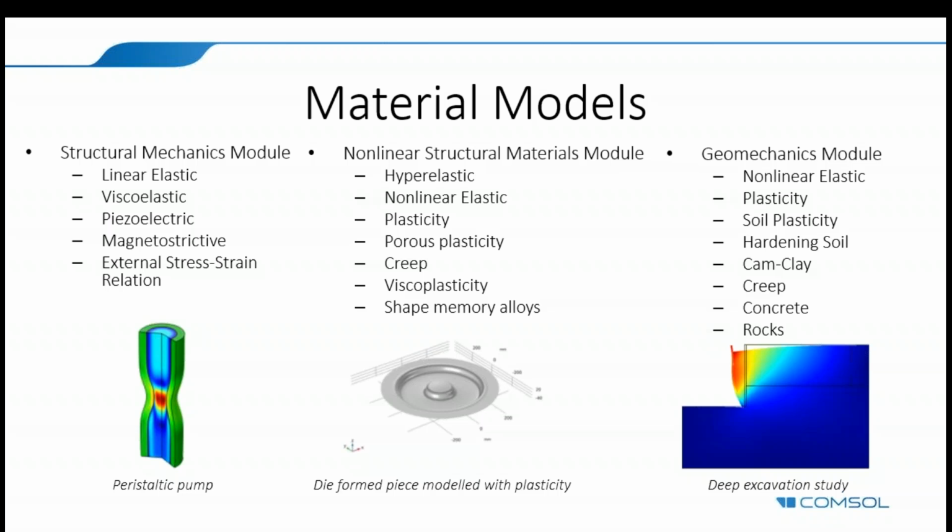Now, the last material model here that I wanted to pick out to explain in more detail is porous plasticity. This extends the elastoplastic functionality to porous materials or powders to allow powder compaction processes to be simulated, for example. This type of material model can be used to track the porosity of the material during the compaction.